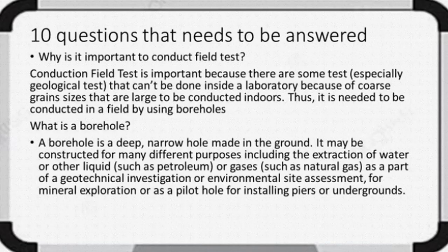So there are 10 questions that we prepared for you. The first question: why is it important to conduct field tests? Our answer is that conducting field tests is important because there are some tests, especially geological tests, that can't be done inside a laboratory because of coarse grain sizes that are too large to be tested indoors. Thus, they need to be conducted in the field by using boreholes.